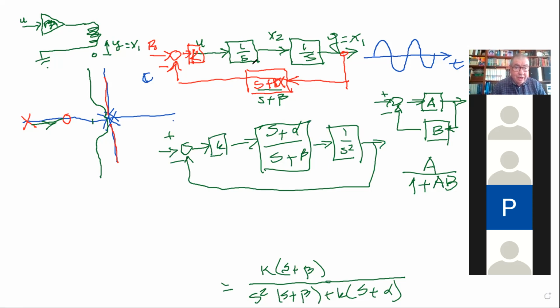Okay, and the difference is that in this case, this zero does not cancel that pole. Instead, in this case, this 0 will cancel that pole. So then you can discuss what is the best option for you. So we have already two solutions. Now, another solution to stabilize the system.